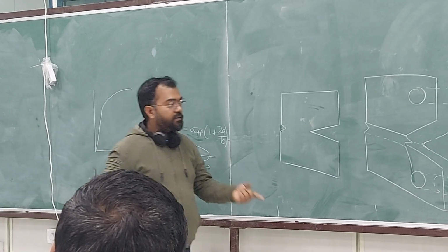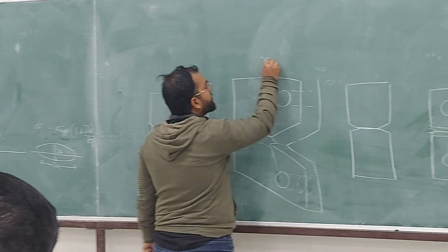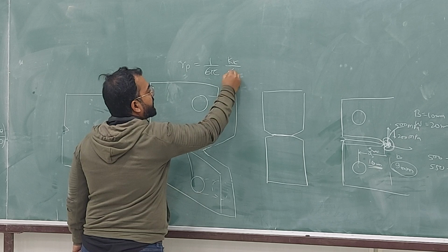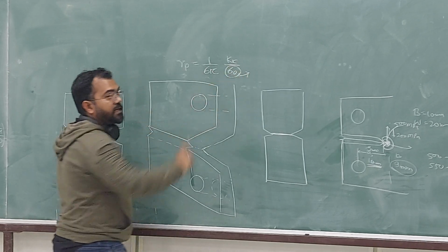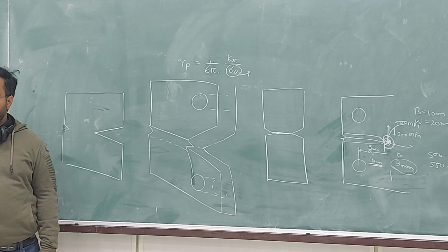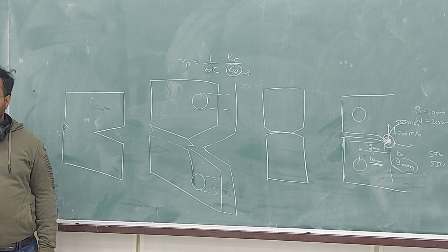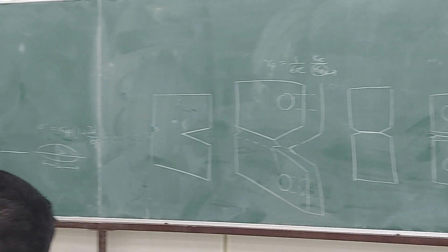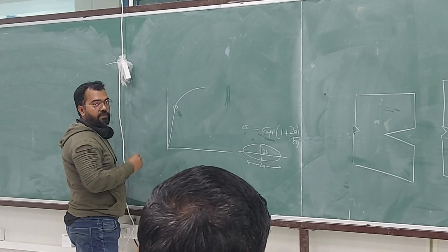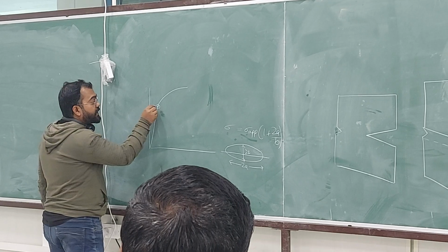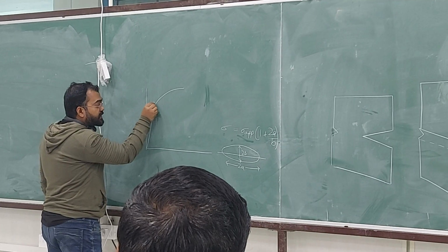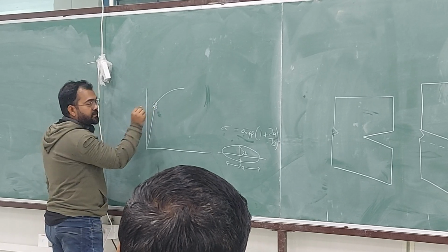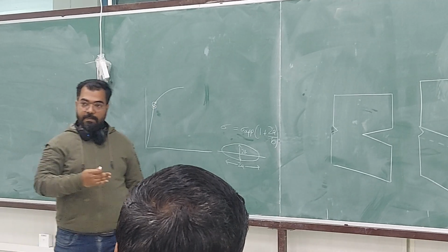Do you understand? So the consecutive plastic zone radius will be smaller, because this sigma naught is increasing for a strain hardening material. For a plastically deformed region, the next sigma naught is higher. So plastic deformation starts here, and for the material which has plastically deformed, further deformation can happen only at higher stresses. It cannot happen at this stress. You can't have more strain than this. Okay?